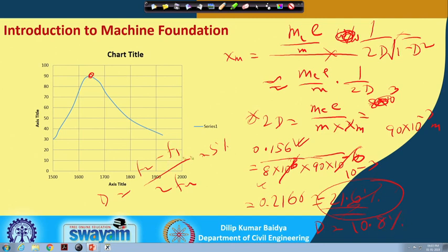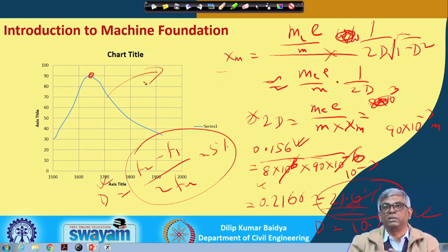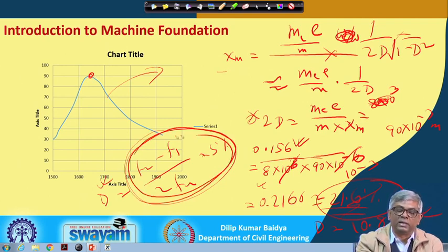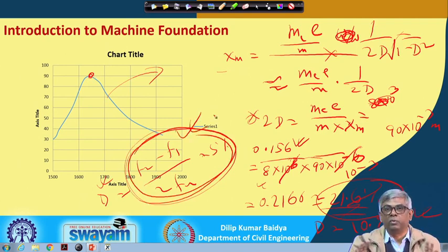From the peak amplitude, when you calculate from this equation, we get 10.8%, but if you use this expression you get 5%. The reason is that from the peak amplitude, the damping is overestimated, whereas with this concept you get the average value of damping. So this is better, but I have explained both methods, and you can use any of these if asked in the exam.